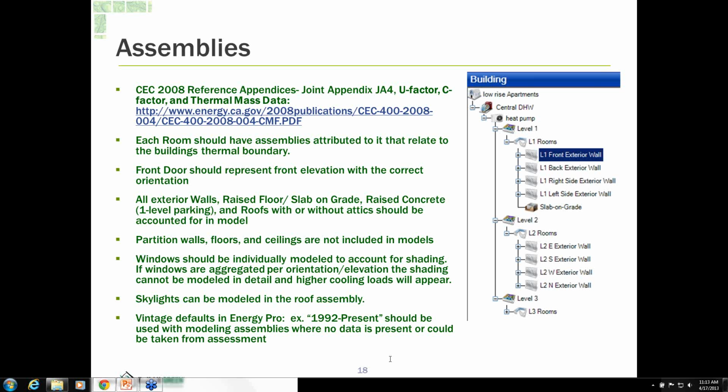But there are errors that will stop you, like if you set the occupancy type to multifamily and you're actually doing a high-rise calculation, it will stop you and say, hey, no, I can't do this calculation because you have the occupancy set to multifamily, not high-rise. And you have to go in and change that in order to run the calculations.